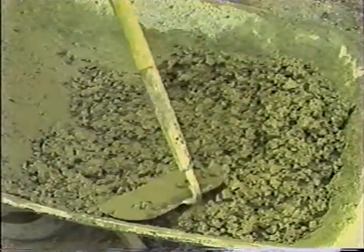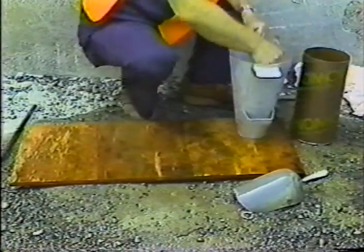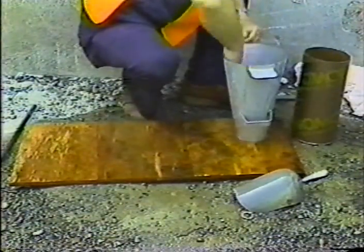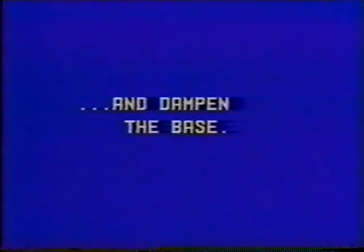To begin with, of course, you need a sample remixed until it looks uniform. Dampen the inside of the slump cone so the concrete won't stick to it. And dampen the base as well.